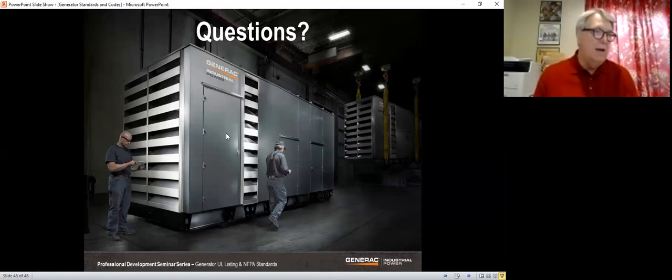One thing I like to have, and it's not always done, but whenever you buy an emergency stop push button from us, I always do this, is I have a clear plastic cover that's hinged that goes over the emergency stop push button, because it's so easy for somebody to push that button. Maybe they're just playing with it. Maybe they push it in to do service, and then they forget to pull it back out, and now your generator won't run. And it could take a little bit of effort to determine that it won't run because of that emergency stop push button being pushed.